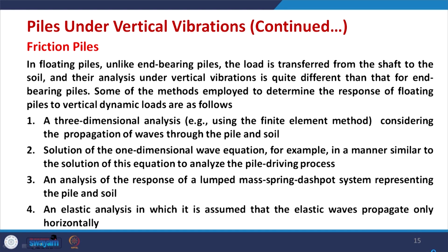So, this was the case for end bearing piles. Prakash and Puri continue with friction piles or floating piles. In floating piles, unlike end bearing piles, the load is transferred from the shaft to the soil. So, basically it is not end bearing action; rather, the load is transferred to the soil itself, and their analysis under vertical vibration is quite different from that for end bearing piles. Some of the methods employed to determine the response of floating piles to vertical dynamic loads are as follows.